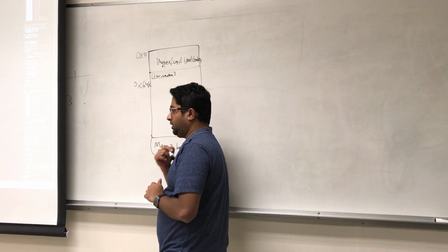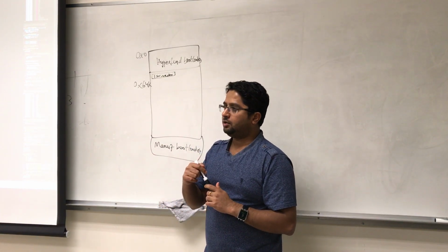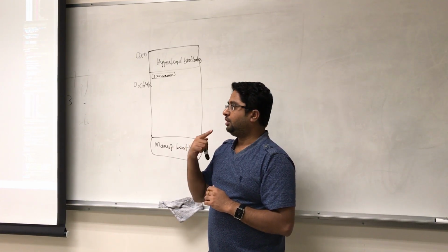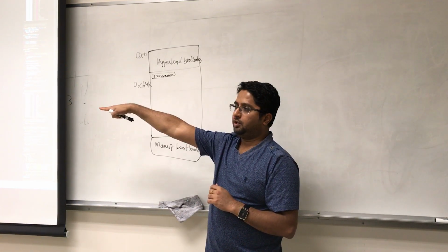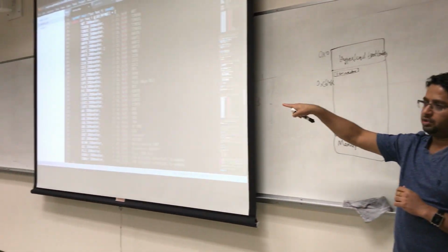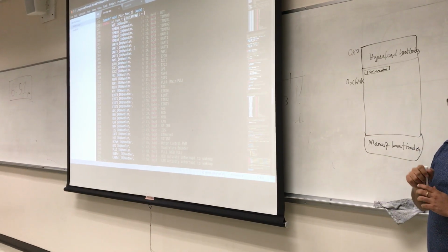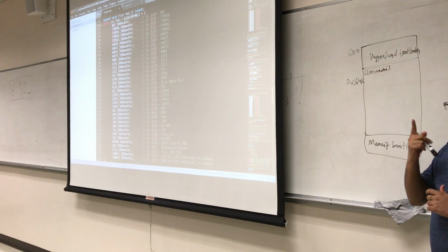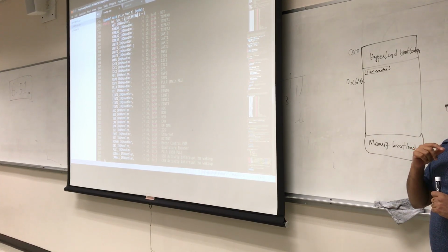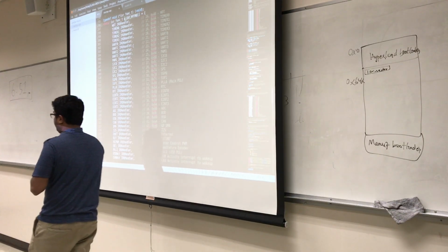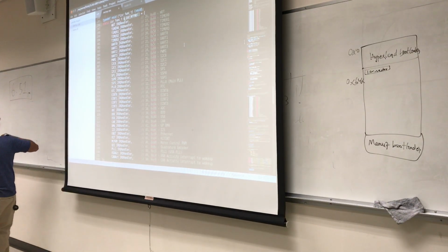So if you want to write an interrupt that needs to be addressed, there are three ways to actually address the interrupt. The first way is to hack up this function and then put your interrupt function name there, which is going to be addressed whenever it gets to it. That's the first way of doing things. And the second way of doing it is, there is a function called ISR_register.